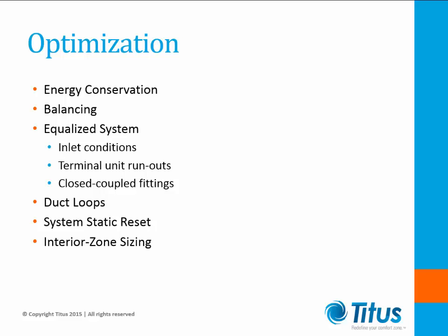Finally, let's look at some means of optimizing your duct design to save energy. Designing low velocity systems is a great start. Utilize 1,500 feet per minute in your primary duct runs in place of old design guidelines of 2,000 or 2,500 feet per minute. Utilize long radius turns instead of 0 radius turns. These will save a drastic amount of energy. Balancing of the duct system and recommissioning also help to maintain energy efficiency of the duct system far past the design.